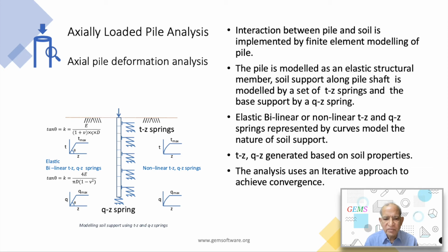The stiffness of these springs are represented by a set of nonlinear TZ curves for each layer and a QZ curve at the pile base. Two approaches are available in the software for developing TZ curves. Nonlinear TZ curves based on API recommendation, and a bilinear model comprising of an initial slope of the TZ curve using an elastic modulus and a parameter zeta based on Randolph's work.